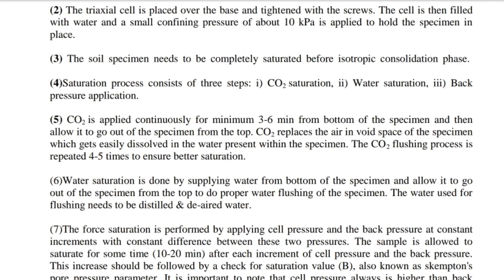6. Water saturation is done by supplying water from the bottom of the specimen and allowing it to go out from the top to do proper water flushing of the specimen. The water used for flushing needs to be distilled and de-aired water.